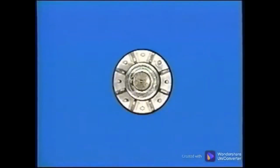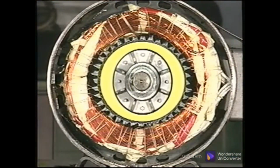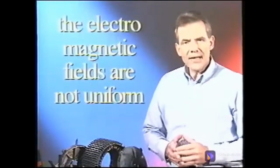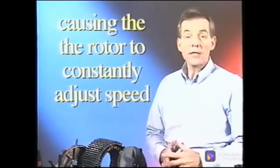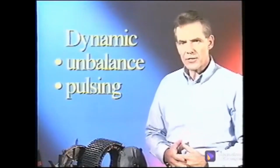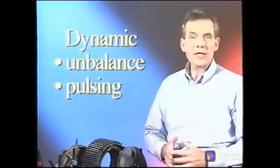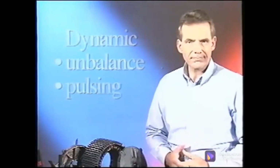The second cause is the rotor may be perfectly round, but the stator is oblong, so that there is more gap on 2 sides of the rotor than the other 2 sides. In both dynamic and static eccentricity, the electromagnetic fields are not uniform, causing the rotor to constantly adjust speed, generating a pulsing vibration. With dynamic eccentricity, the eccentric rotor may be unbalanced and therefore exhibit characteristics of unbalance as well as the pulsing due to uneven flux.